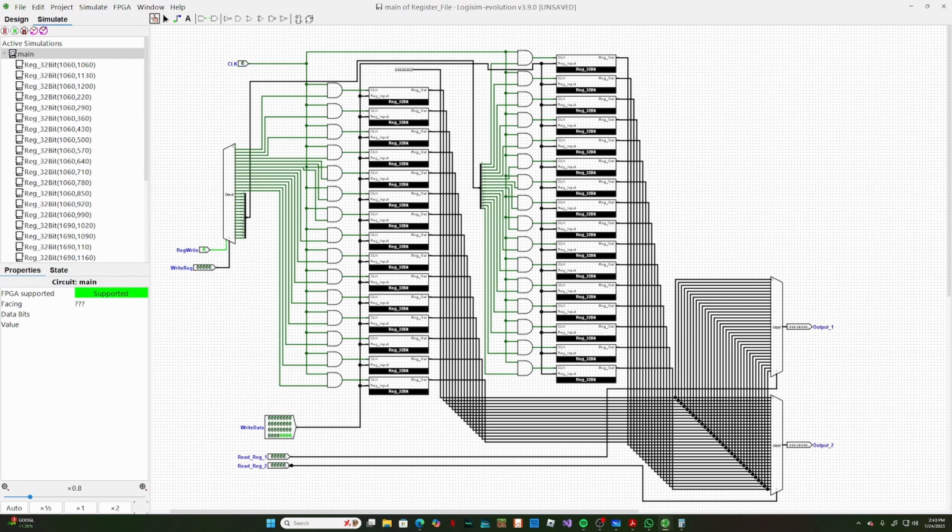The file register, even though it looks convoluted, is very fast. It's small, but it's also faster than RAM because it's right there in the action. It doesn't have to deal with addressing delay or cache hierarchy. It's right next to the ALU. It's always ready at all times. All of this is combinational logic.